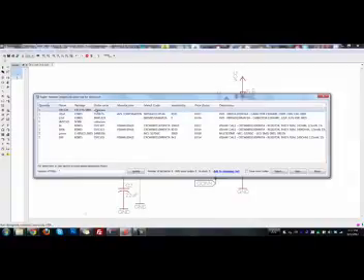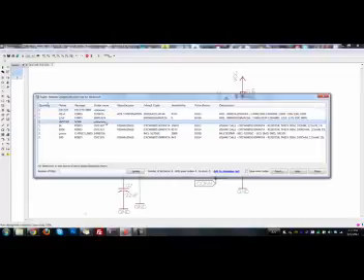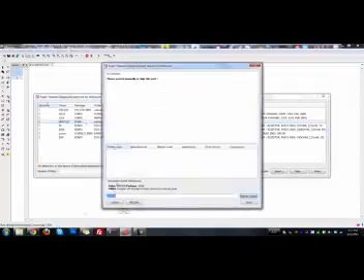That's fine. We're going to order the battery clip from Adafruit because that's where we got the footprint from. But the 555 timer, we should be able to find in an SO8 package. So let's have it try to look for that again. Let's look for just 555 timer.